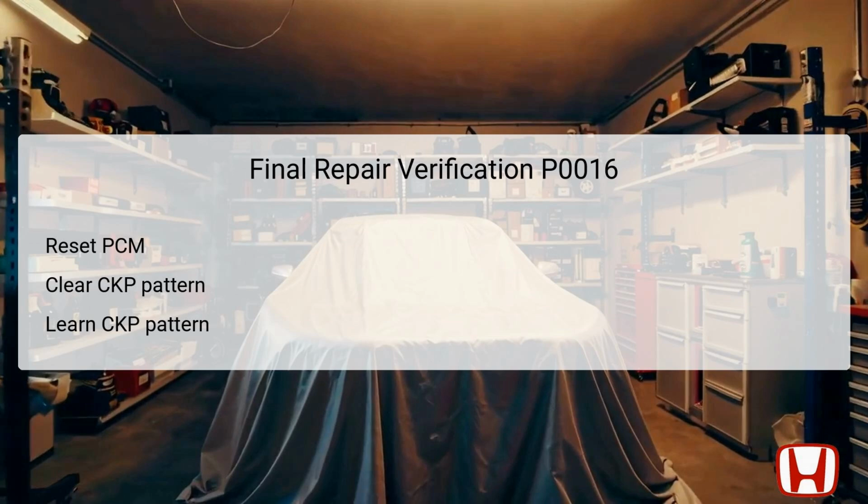Once the CKP pattern is cleared, proceed with the CKP pattern learning phase, where the PCM recalibrates itself to understand the engine's timing once again. This step is essential for restoring proper functionality and performance of the engine. Ensure all verification steps are documented, as they confirm the effectiveness of the repairs implemented.